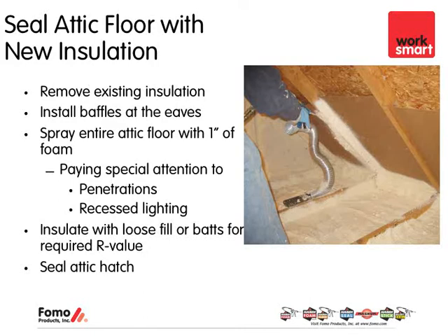You want to pay special attention to, again, the same areas: penetrations, recessed lighting, electrical conduit, things like that. Then you want to be able to backfill with whatever R value. In some cases you may have so many penetrations that a critical seal just may not make as much sense, and you feel much more comfortable going in with an entire 1 inch over the foam. You're creating, in essence, a hybrid insulation, and you're again stopping all that air infiltration or exfiltration out of the house.